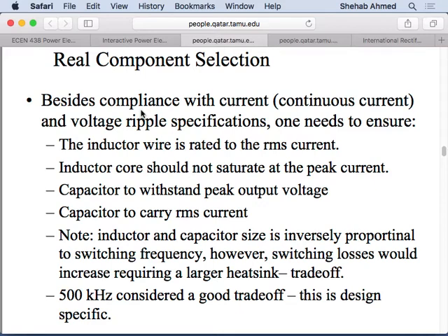Anything above that will give you continuous conduction mode. Anything below that will be discontinuous conduction mode. You can take this L minimum and go to inductor vendors. There are vendors that sell pre-wound inductors at certain values. They would sell you those, right? So you tell them I would like a certain inductance, and you would have to tell them what your peak current is.